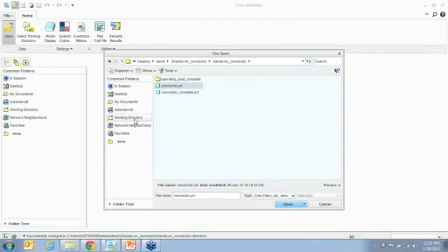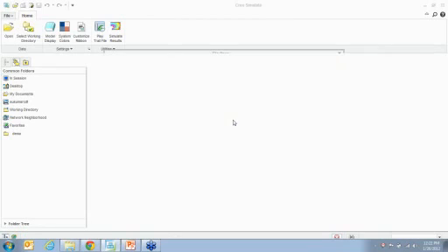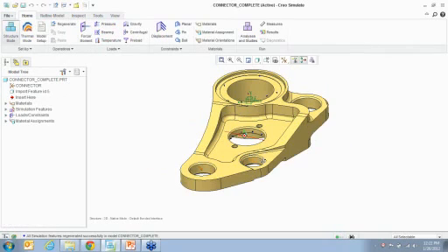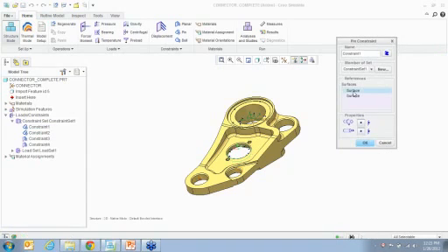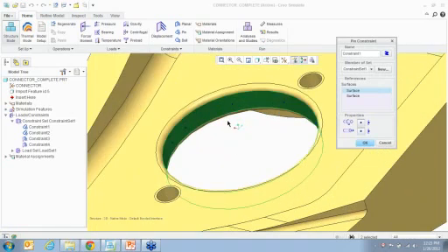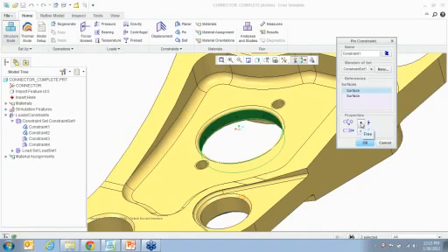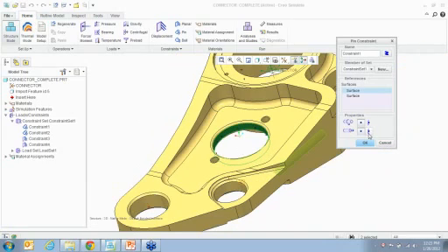another example for this. Say we have a connector part. I want you to look at a couple of constraints that are new. If you're with Wildfire 5, this was there in Wildfire 5. If you're in Wildfire 4, this would be new for you. So if you right click on these constraints, you can see that you've selected two surfaces, and you're basically creating a pin constraint saying that it's free to rotate and translate about the axis. You can say, hey, I only want you to rotate, I don't want you to translate. You can make any of them fixed or free, and this is new.